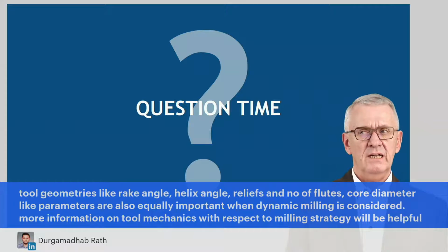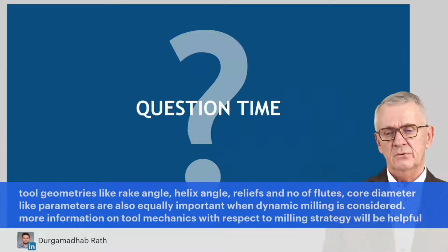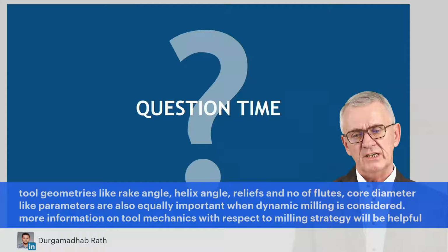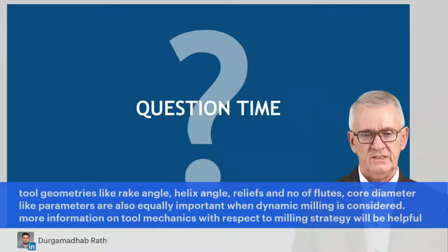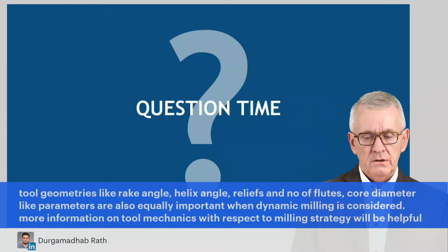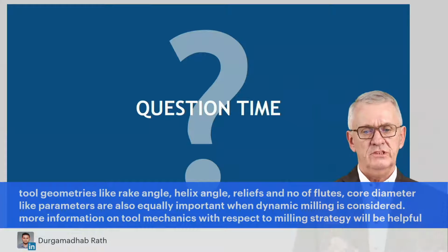Dynamic milling, my definition of it, remember what I said, dynamic milling is a situation where I do realize that the conditions in which a milling cutter is functioning are changing in time, and cutting conditions should be modified to compensate for that, my compensation principle. I think geometry is variable number one in those things. The example I gave you was the radial depth of cut and the diameter of a milling cutter, and how the ratio is between those two.